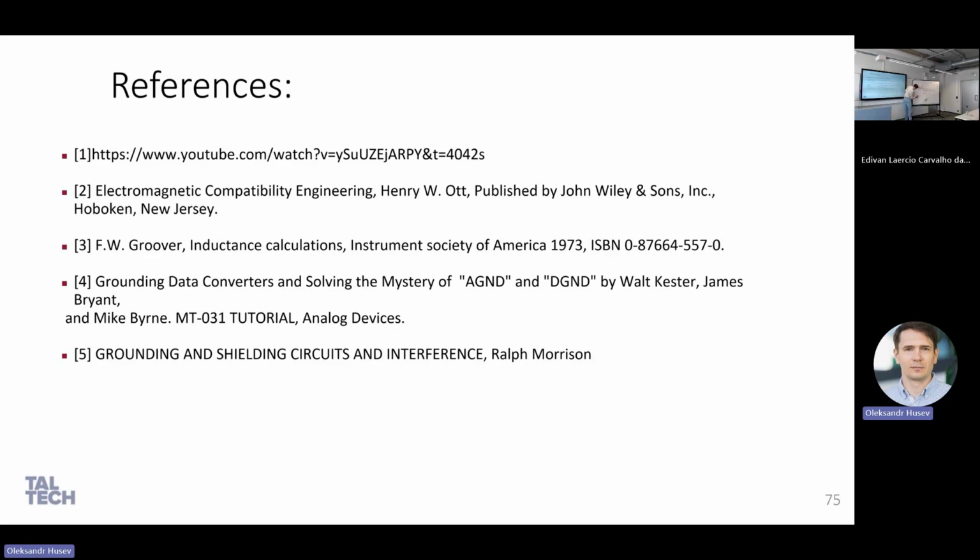I will put the drain very close. Have I minimized inductance? Definitely yes. And in case of hard switching, it's definitely enough. But if I want to minimize even more and add extra capacitance, I would use the second layer, right under this layer, and put a drain current path like this, and even thicker. You see, it adds direct overlapping, it minimizes inductance and adds capacitance. So your drain-source capacitance is increased.